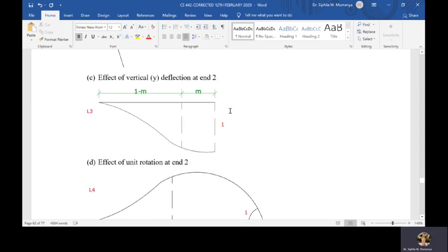shape function, and this is the function of displacement at any point for an element subjected to bending. If you give a unit vertical displacement, for example, at node 2, the rest of the shape of the element will be like that, because at node 1 it's 0. So we would want to know at every other point, because it's not linear, we need to know how to determine that, because it's very important.